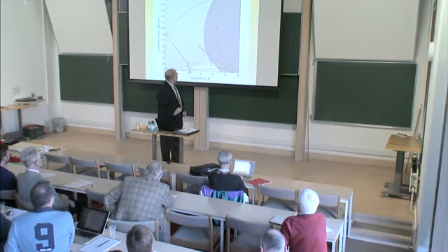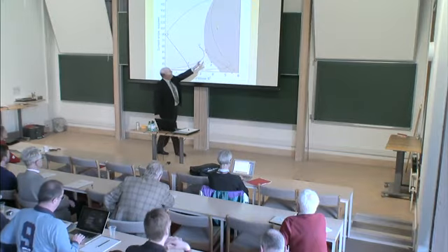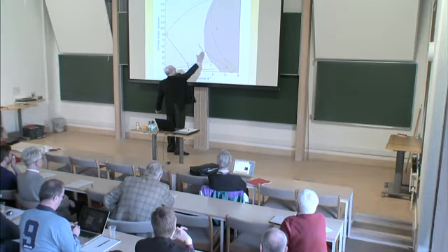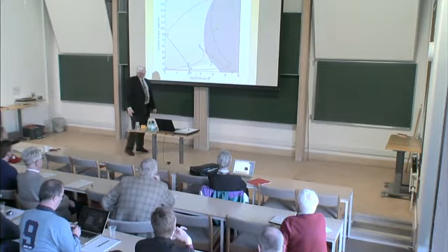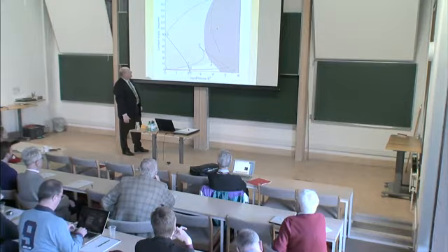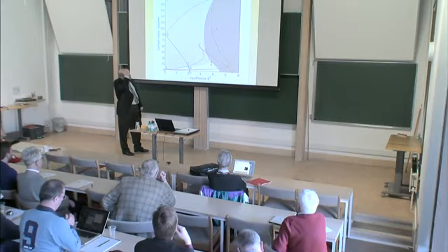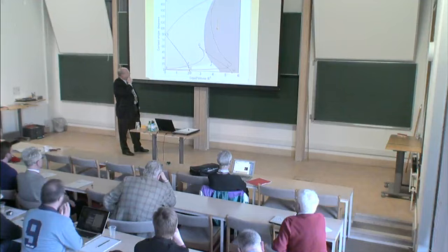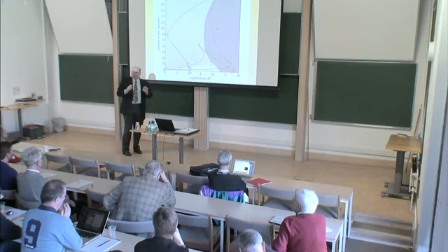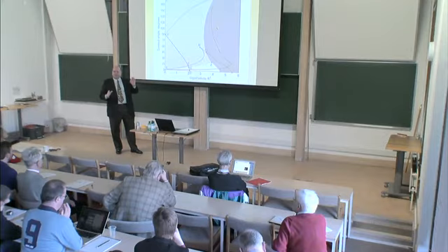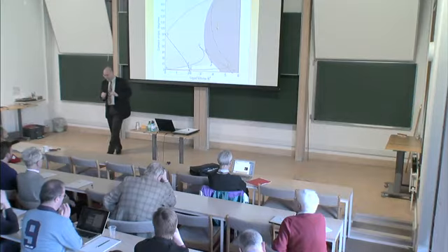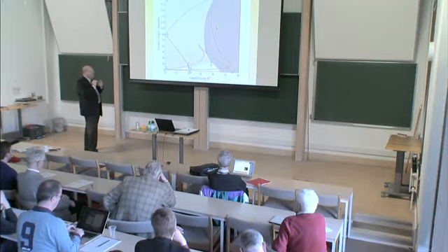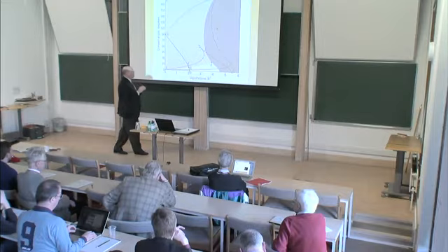I would say you probably break at this point, because from here the plug is the minimum energy and over here the droplet is the minimum energy. So you might drop to one or the other. But I think one must be careful with Evolver. It's very easy to look at what's going on on your screen and assign physical significance to changes, but Evolver is not computing motion. There is no d by dt in Evolver. The Navier-Stokes equations are not in Evolver.